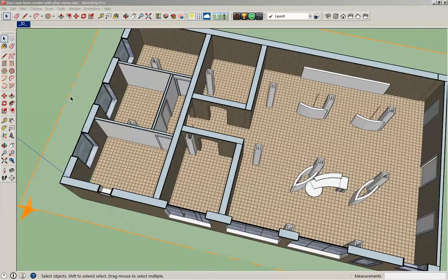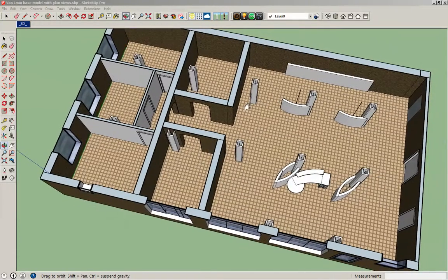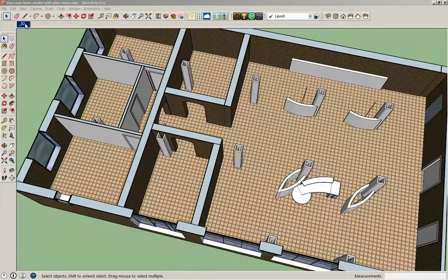The only thing is that it's kind of nice sometimes to turn off this section plane. This orange bounded grayish kind of area is called the section plane. And you can control that separately. Just under the pull down menu, you can uncheck section planes. You see how it's no longer visible. And I like this view, so I'm going to save it as a scene.